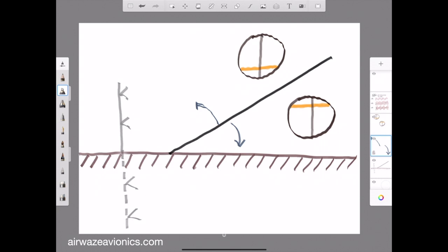As before, an increase in the depth of modulation of the 90 Hz signal means the needle will deflect to the low side of the glide slope. The aircraft is too high. An increase in the depth of modulation of the 150 Hz signal means the needle will deflect to the high side of the glide slope. Remember, we chase the needle on the glide slope, so if the needle is low, the glide slope is below us.